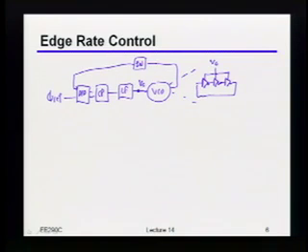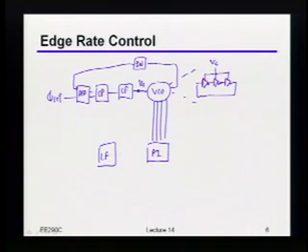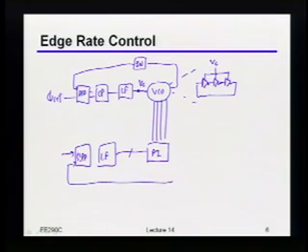Okay, so indeed, what you're basically going to do is build the rest of my dual loop CDR. Again, I take my multiple clock phases out of the VCO, and I feed that into some phase interpolator structure, and we'll draw that in more detail in a second. Of course, I'm going to have some sort of loop filter that's digitally controlling the phase interpolator. I have some bang-bang phase detector.